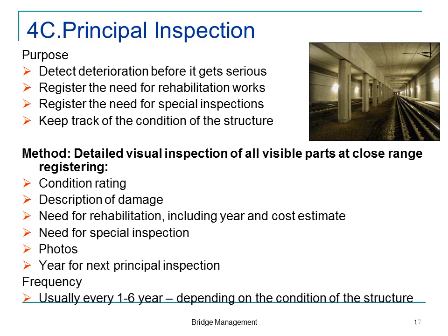If you have a large bridge and you see the concrete cover has fallen off in a number of positions, and you know there's a lot of water and salt in the environment, then you will immediately say there's a need to do something here, and you would make an estimate of what it would probably cost to do this or that.